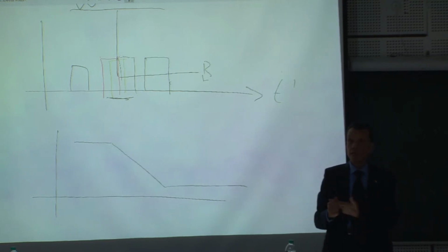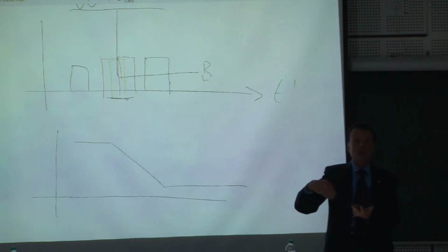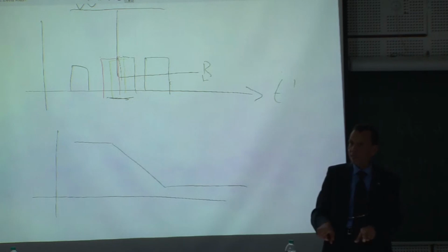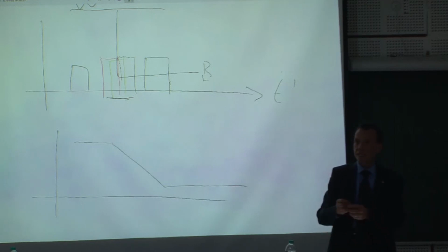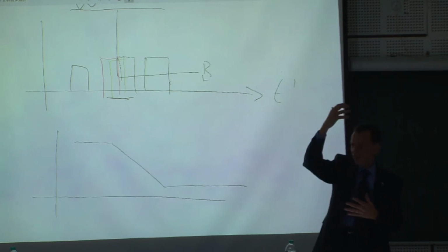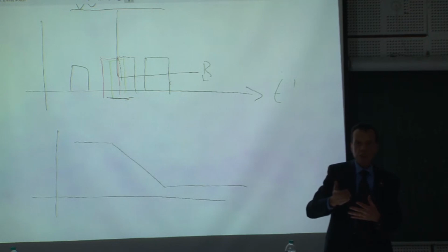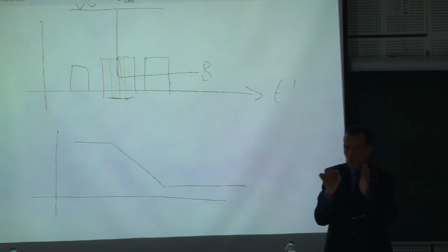So we consider today two artifacts: the multiple image, and how you can remedy it without paying with the bandwidth by just signal processing. The second artifact is the blurring. Blurring means that things are spread out. So instead of having a sharp edge between black and white, you see a very small range, depending on the bandwidth, a small range where you go gradually from black to white through gray.